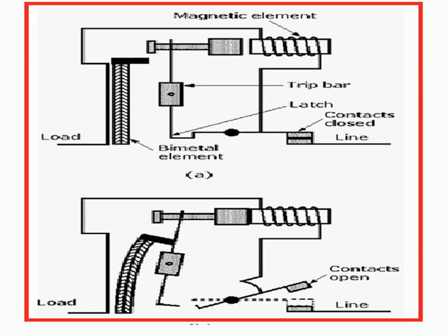Number 1, as per the thermal effect, the bimetal element is subjected to the flow of normal current, meaning less than the specified value of the circuit breaker. Hence there is no temperature rise in the bimetal element. The current flows through the magnetic element, then it is connected to the latch, and the moving contact and fixed contact are in contact. Hence the current flows through the electric circuit through the MCB in this manner.